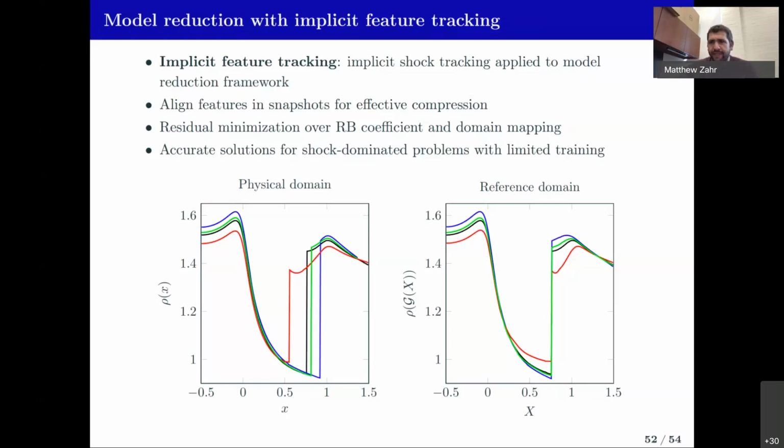We don't let it adapt every single iteration, otherwise you would not be convergent. We only allow it to adapt at some frequency. And once the residual drops below a certain value, meaning you're in the convergent regime, we disallow the adaptation of the parameter. So it's adapted to balance those two terms, and eventually cut off because we don't want it to impede convergence.